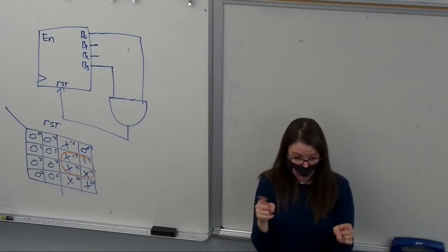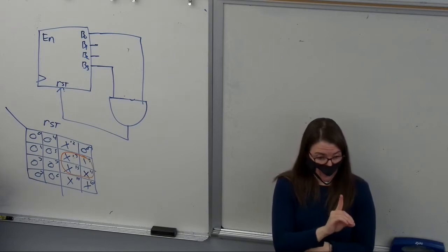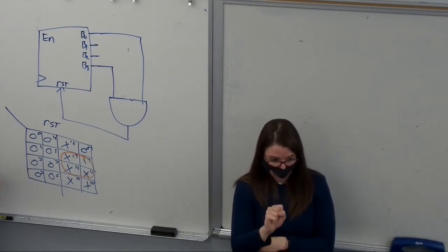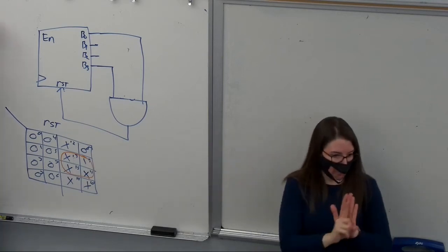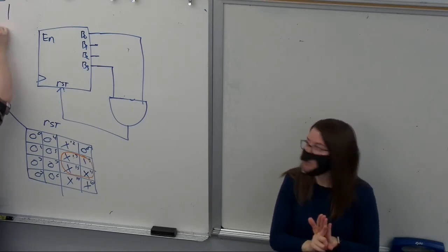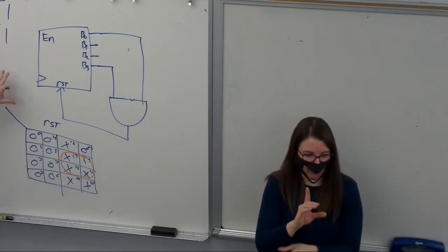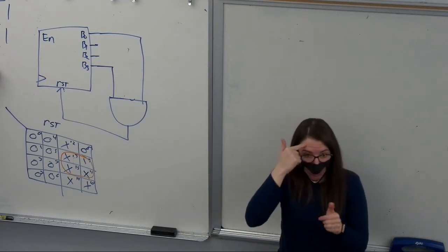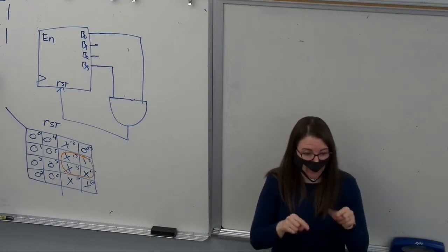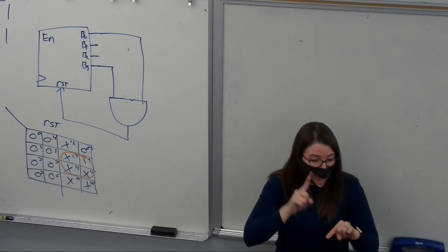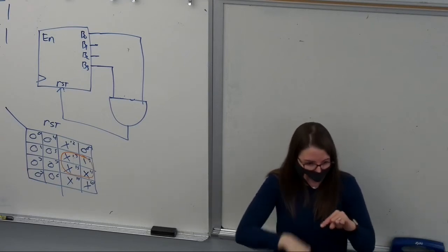Okay, so BCD is probably going to end up on the exam, just so everyone knows. BCD is where we take 4 bits and assign it to a decimal number. That's why I stopped at 9, right? This is your alarm clock. We tie it into the 7-segment display, right? And then each of these logics correspond to lighting up 1 decimal digit. And so after 9, we don't care because I can't represent 10 on a 7-segment display. That's what BCD is. It's just coding decimal in 4 bits of binary and saying everything else is don't care.